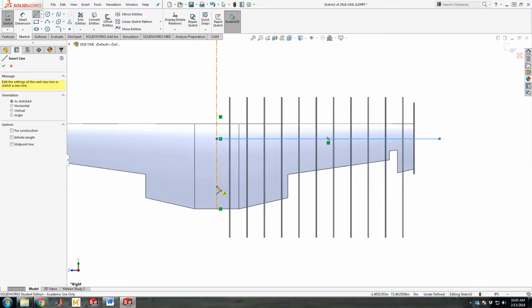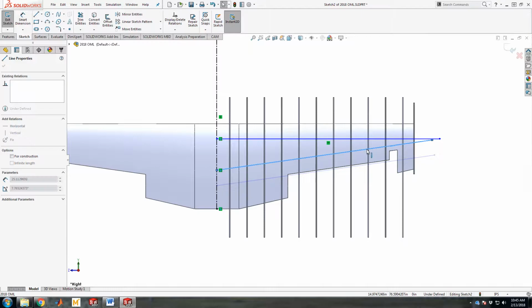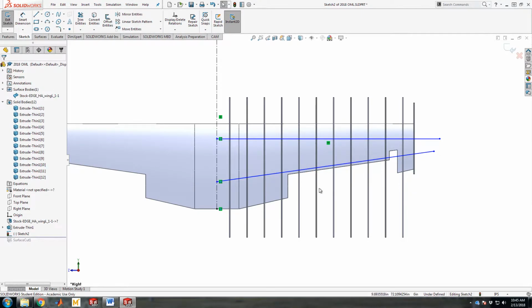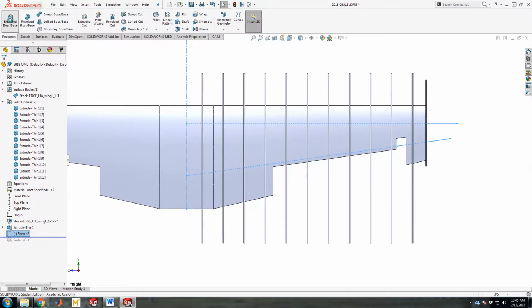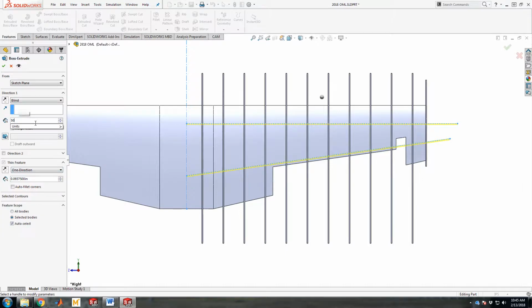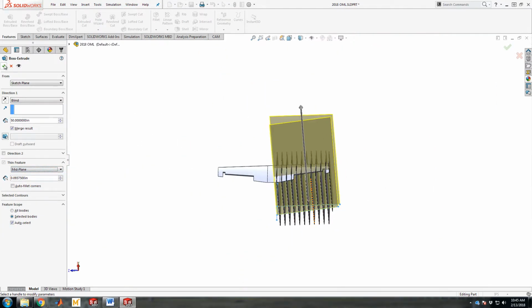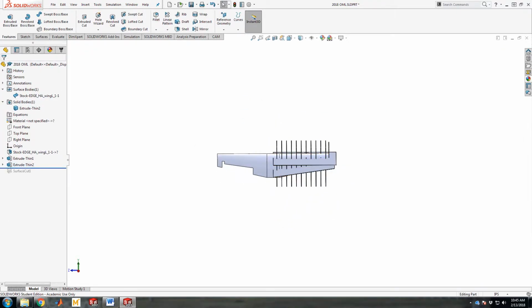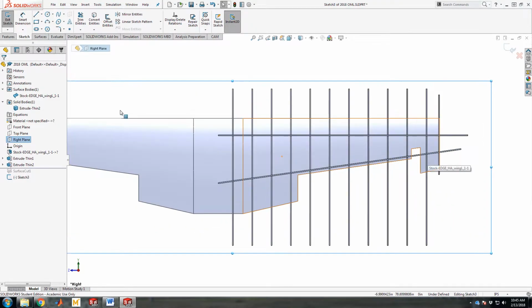Let's put another spar back here. This one is going to be slanted. In fact, I want to get it right inboard of that control surface, because in reality you'd want those hinges and the connections to be attached to something. Yeah, let's do that. So a thin extrusion, same as before, one direction, 50 inches tall. You change that to actually mid-plane. That'll be sufficient. Now we have one more sketch to make, which will be our solids.